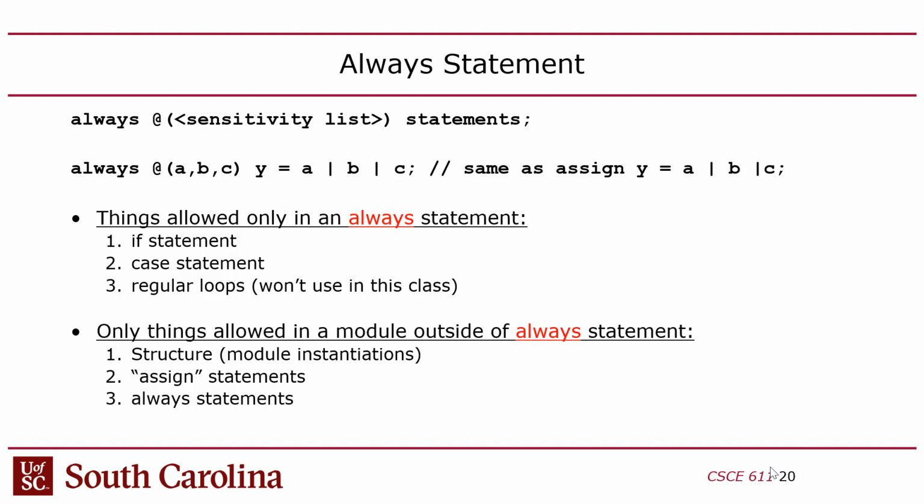On the other hand, if you have a clock in here, if you have a posedge clock in the sensitivity list and you don't have inputs like A, B, and C in the sensitivity list, then it creates memory, because the whole always statement triggers just when the clock event happens, right? So any inputs that change outside of the clock are just ignored. You end up with flip-flop type behavior, where inputs could change but nothing happens until you get that clock edge, and then the inputs are sampled by the always statement and the outputs update.